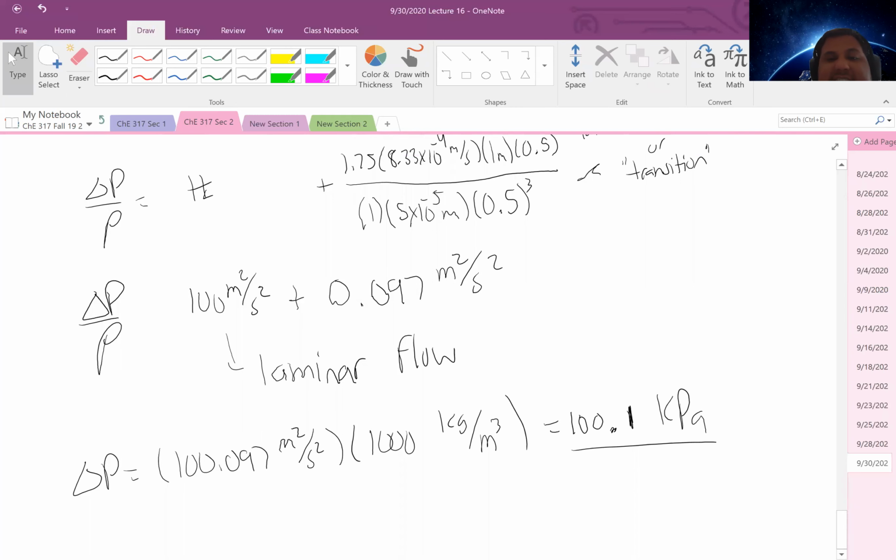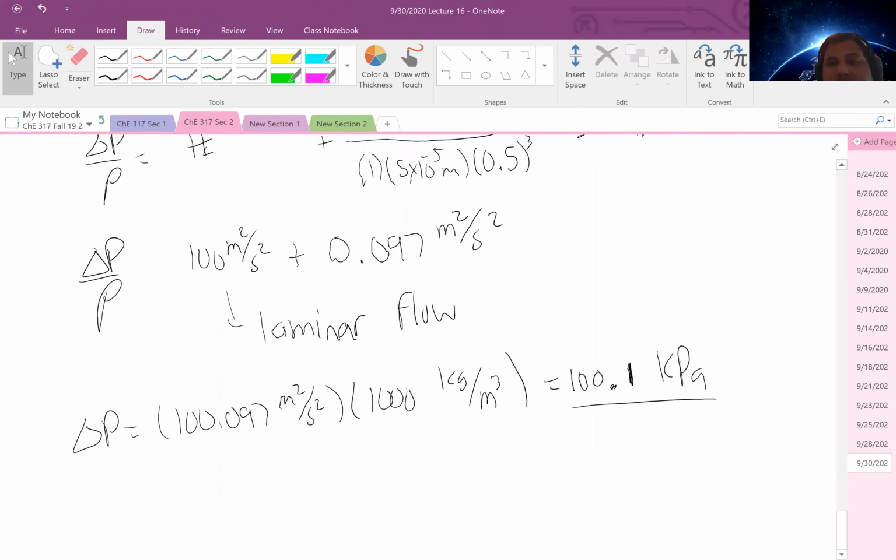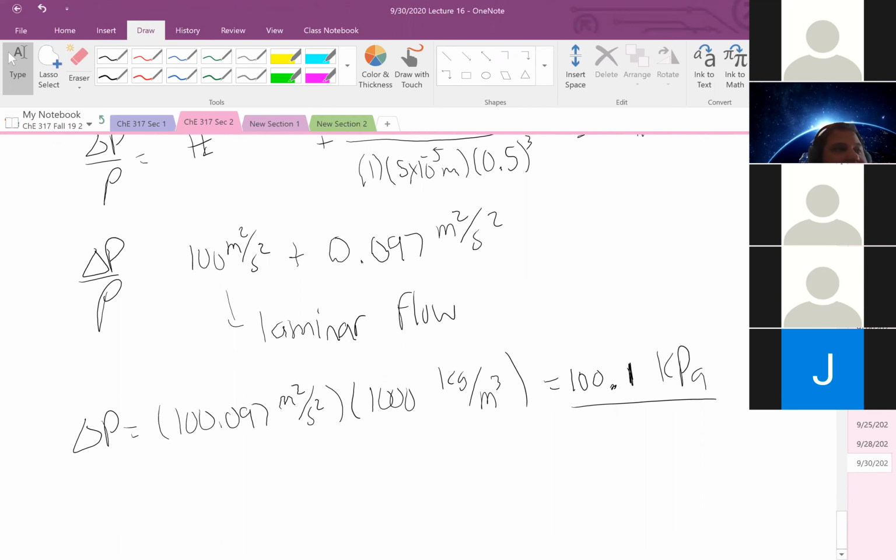So any questions on that example? Any questions on packed beds, the use of the Ergun equation and how we have essentially two terms that make it up? Two terms that define the Ergun equation, one constituting pressure drop for laminar flow, and a second accounting for turbulent flow, which, depending on the flow situation, we can neglect, strictly using the Blake-Kozeny or the Burke-Plummer expression.